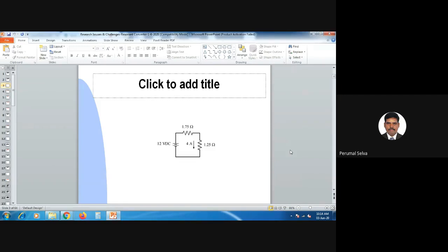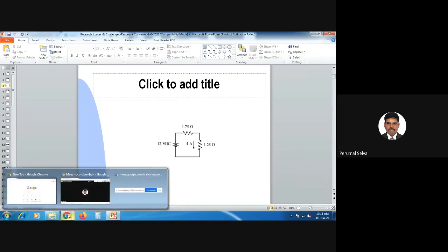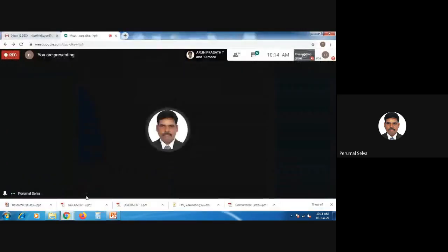Second problem with the circuit, the lack of regulation. It is rare that a primary source is absolutely constant. For example, the voltage of a 12 volt automotive starting battery can vary as much as plus or minus 2 volt, depending on whether the battery is being charged, 14 volt, or if the car is started while the head and tail lights are on, so it goes down to 10 volt.